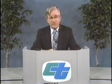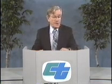The simplest form of a circular curve, and the one most often encountered in surveying, is tangent to and connects two tangent sections of a route alignment. The basic components will be shown in the next few graphics. There is no universally accepted terminology for the parts of a curve in surveying practice. Every surveying company or public agency seems to have different curve terms and abbreviations. Therefore, I will be using terminology and notation that I am comfortable with, having lived with them for the last 30 or 40 years. Let's first look at the intersection of back and forward tangents of a soon-to-be formed circular curve.